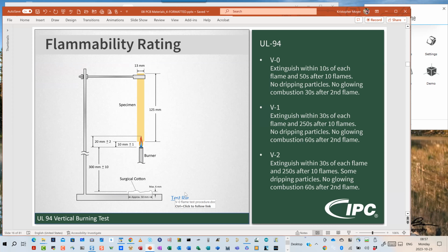Well, because they're testing for safety, one of the safety things that they test for is flammability. In this case, it's Underwriters Laboratory standard number 94. So UL 94. There are two test conditions they're going to try for here: vertical burning and horizontal burning. We are primarily going to be concerned with horizontal burning. That is going to be our best test.